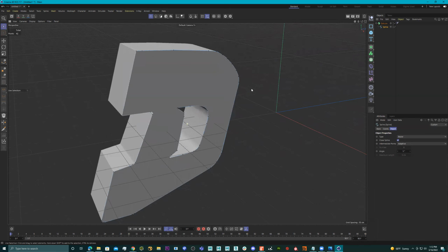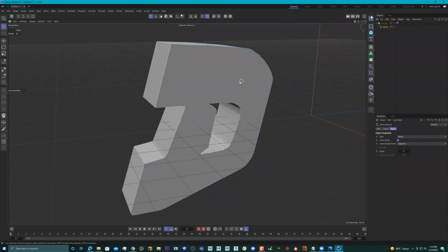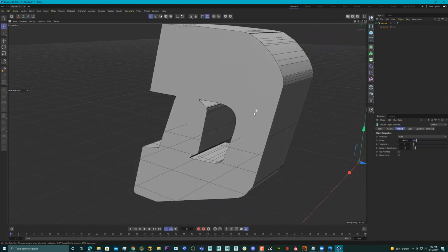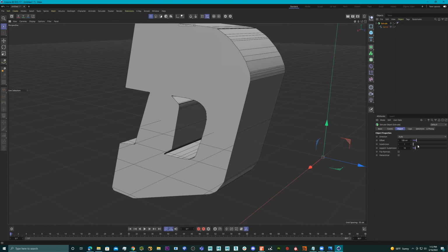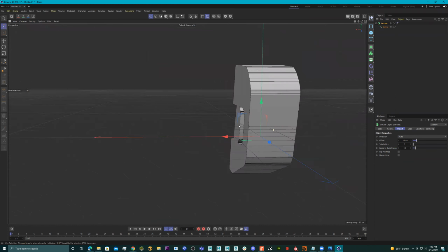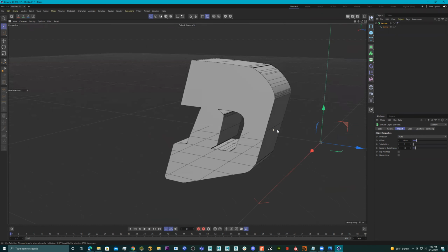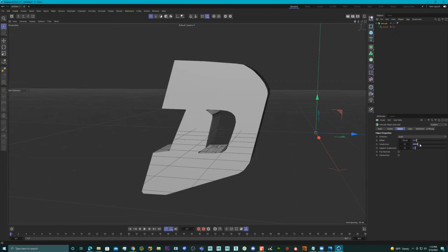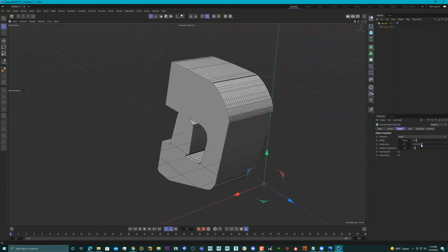Now the extrude options work just like the other ones do on other polygons. So if I type in NB, we can see the wireframe. And let's look at our extrude options. So right now it says direction automatic. Remember, we usually draw these things in the front view, but for whatever reason, the front view is this way. I don't know why I did that, which is usually in Z. So you have subdivision, which is adding the amount of divisions to what I call the 3D.